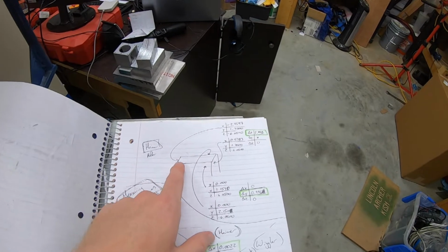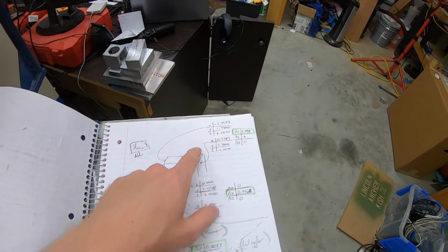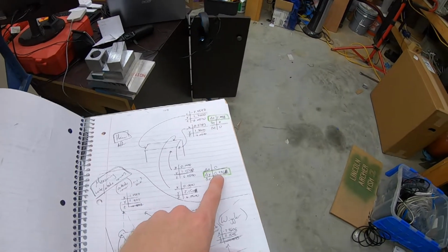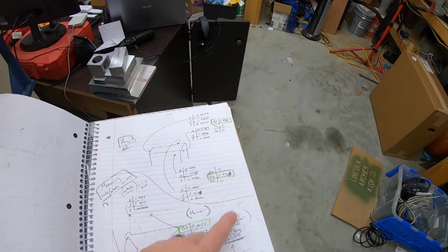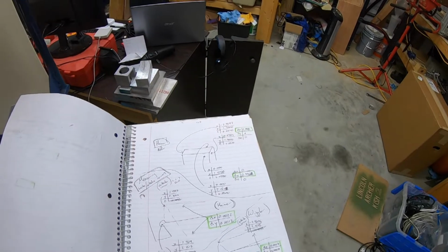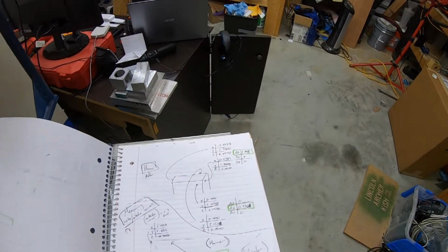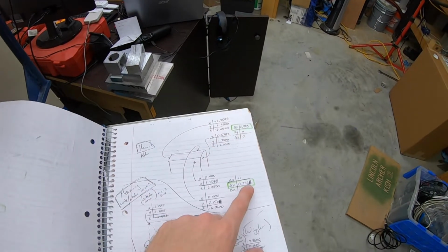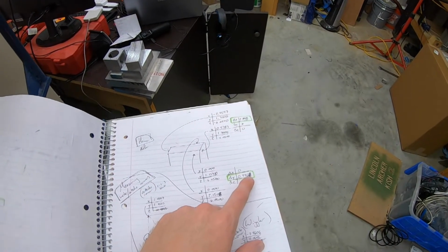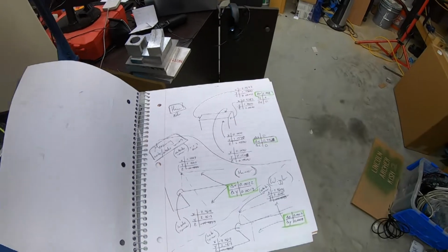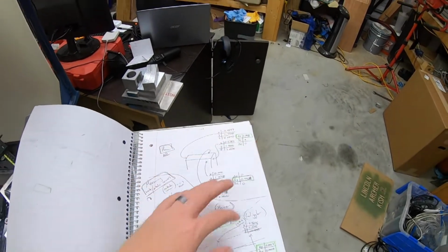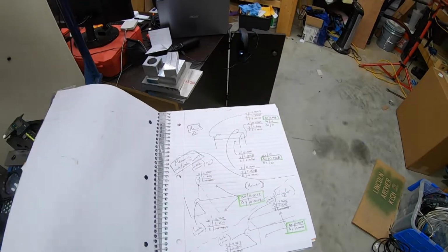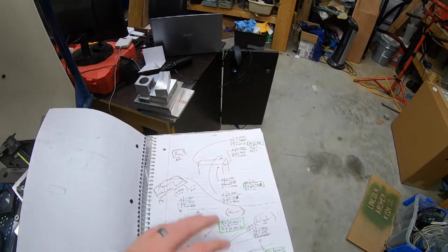So this should be 3 inches, and this should be 1 inch. I got 2.998 and then 0.9968. So that still wasn't the best. I mean, that's 2 thou, and this is a little over 3 thou. But this is a lot closer. This is 3 thou different versus the 44 and 45 thou. So I did that, and then I was like, okay, fine.